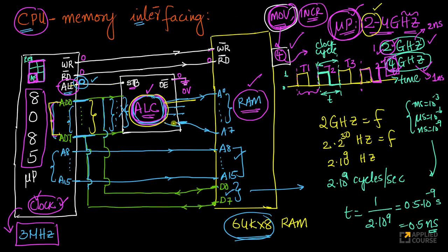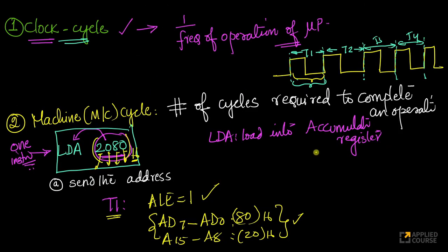The same values will be here. So as far as the RAM is concerned, it is seeing all of these 16-bit addresses, even though the processor is not sending addresses anymore. Whatever address it was sending earlier, we copied into the address latch chip, and we are now making the same values visible here because my OE is set to 0. Very simple concept till now.